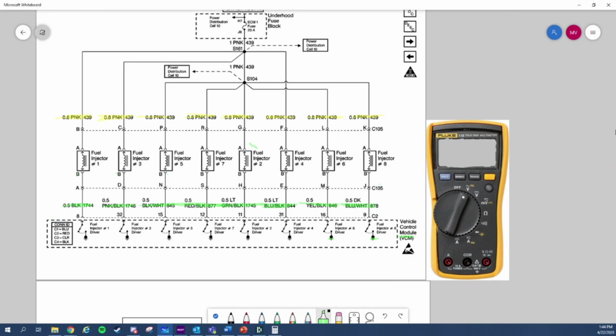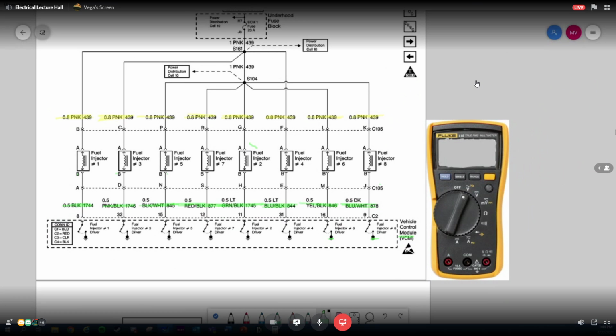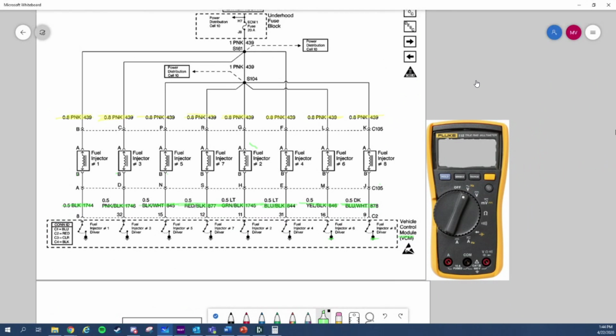Let's go back to carburetors. How did carburetors work back in the day? You had fuel coming out of a carburetor, right? It literally just dumped fuel into the air and it sucked it in. Exactly. It just dumped fuel into the intake manifold, and when the piston was coming down, it was sucking up air and fuel, and then you have an ignition. It was timed with your distributor and your ignition, but the fuel was not controlled by a computer. It was just controlled by gravity and the vacuum from the piston. So that's all it was.